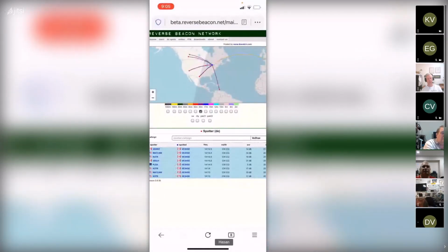Okay. Oh, here we go. Ooh, that's your 20 meters. That's my 20 meters. This is from an hour ago. You got an excellent takeoff angle on that thing. That's nice. I think it's because this is a 5/8 lambda, so it's like the optimum angle. And nothing's cut properly. The radials are just roughly the right lambda over 4. And I use an antenna tuner. That's okay. This is a perfect application for NEC. I've gone nuts using NEC. I think the only conclusion I've come to is I gotta have a good ground. That's the next thing.